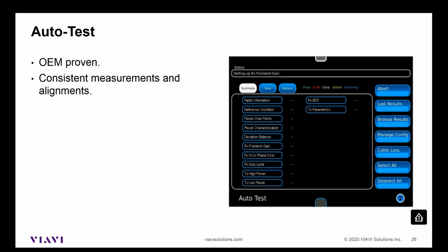I mentioned the proper testing and the proper measurement of our radios. One of the things that goes along with that is consistency. And if you have 3 different technicians testing radios, I can almost assure you that you have 3 different alignments occurring. And Bob at the left may say, well, I'm old school, and I think that putting a little more deviation in makes the radio perform a little bit better.